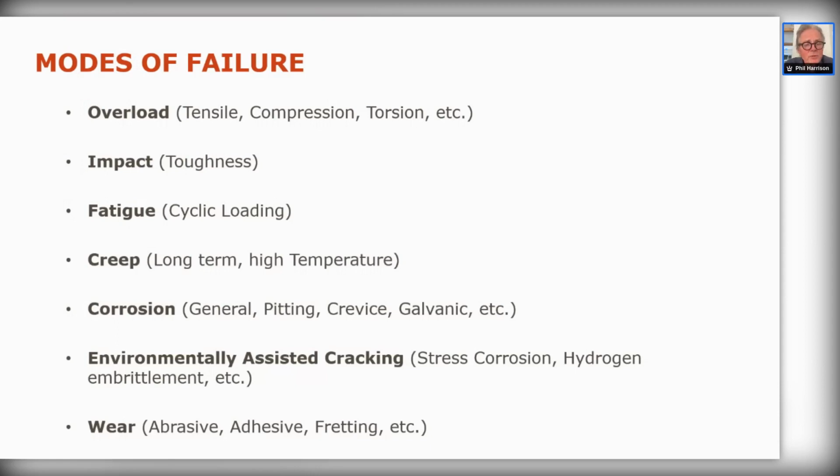And then we have wear. All different things. These are abrasive, adhesive, fretting wear, etc., where we are rubbing materials away in some way or another. Wear is covered by what's called the science of tribology, in which various things are used. For example, different materials against other materials. We have lubrication, we have loading, whether or not you have abrasives within something, whether it's liquid contact, or contact between metals. Lots and lots of different things can happen in there. So lots of different types of failure.